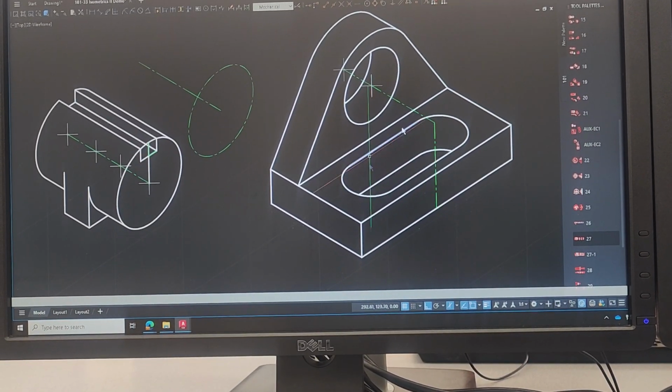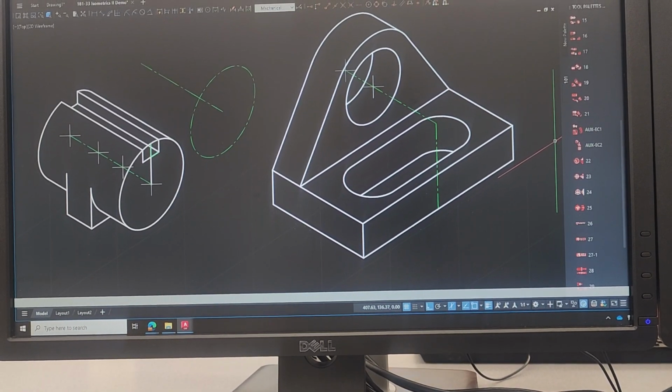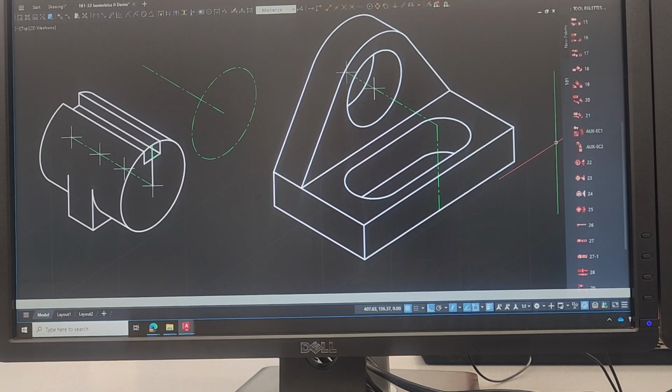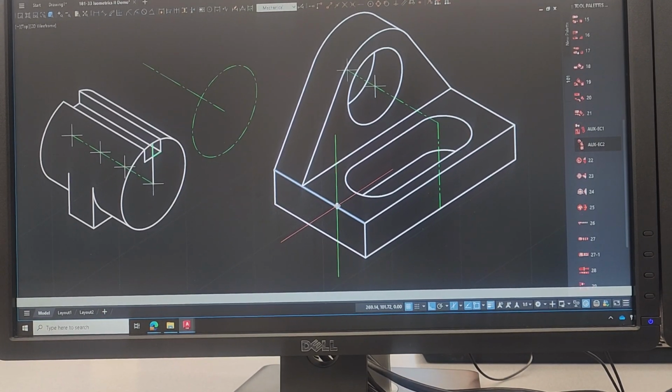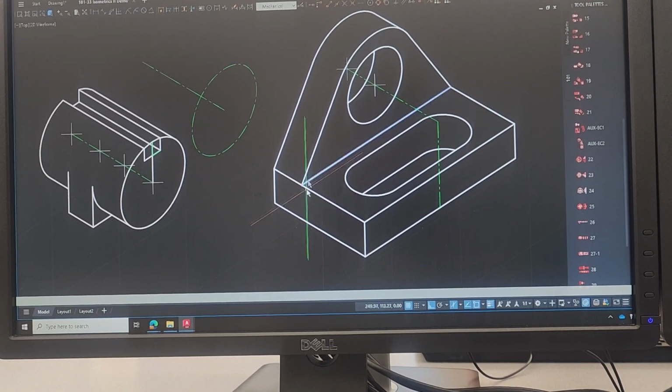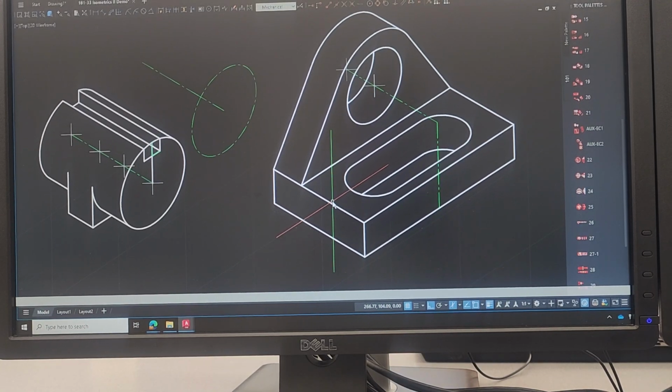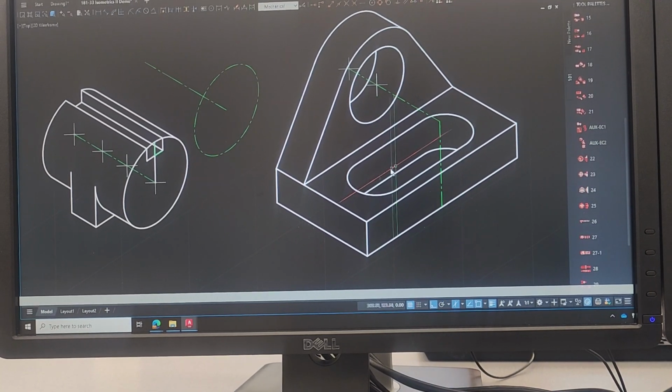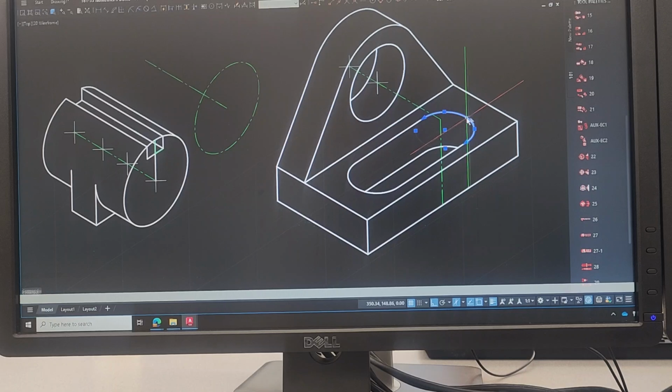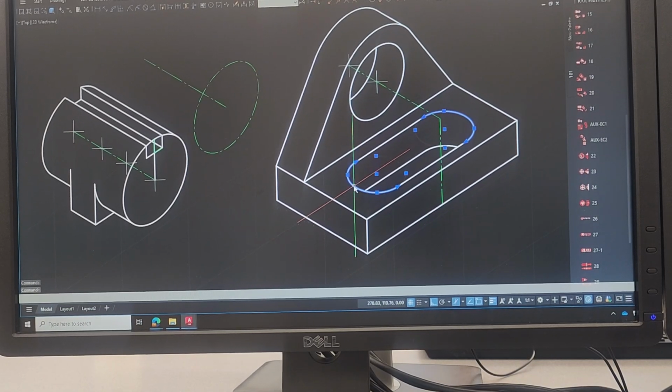Same thing with this guy right here. Make sure that you're setting it all up. You see where the center points are. It's 30 in and 50 to the next. I can start here from wherever that distance is to 22. See it right there? Come back 22. From that position, go in 30, and then from there, go another 50. That gives me the center point I need for an ISO circle there, center point for an ISO circle there.